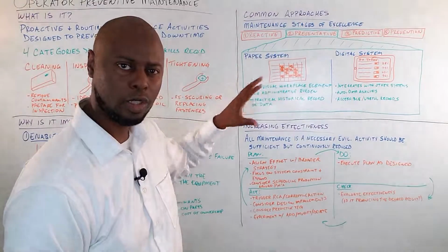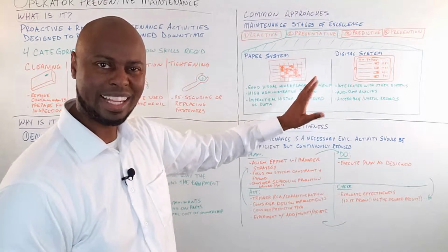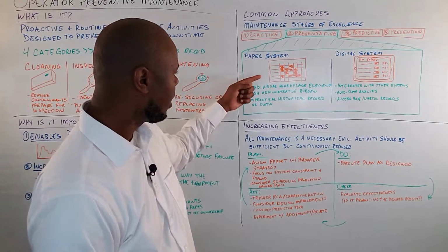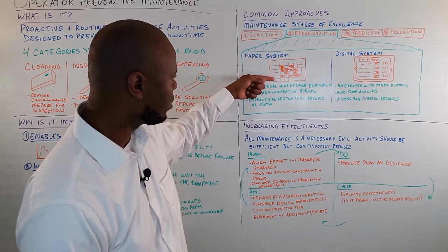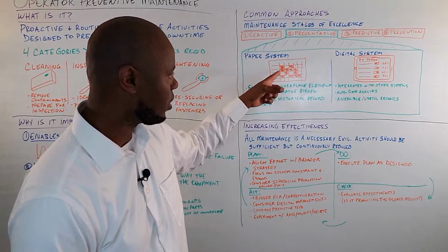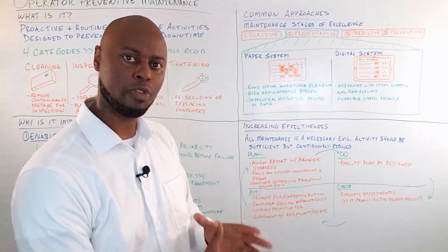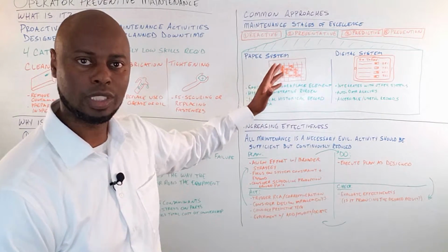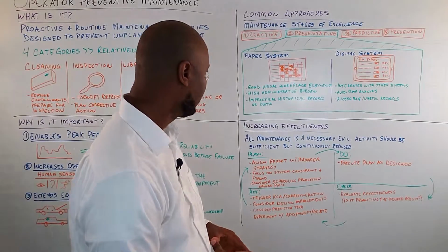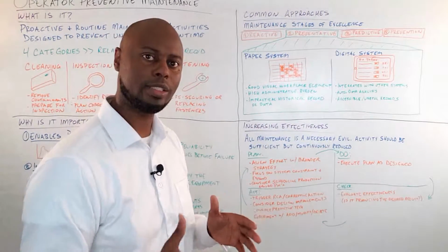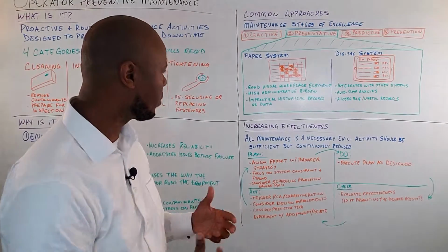It's usually a grid posted out near the line, ideally, and becomes part of the visual workplace for that line. Essentially you've got a list of items here and dates up here, and on a given day, it spaces out when each preventive maintenance action should be taken and by who. You may put initials in there to mark who completed the action. Again, it's part of a good visual workplace element. A visitor to that area can quickly see what's being done, what's not, what's the health of the PM program.